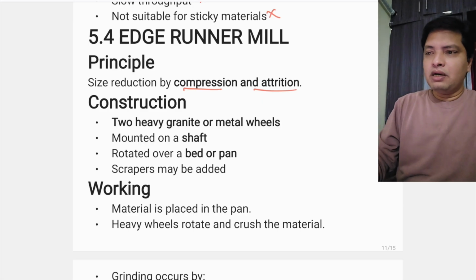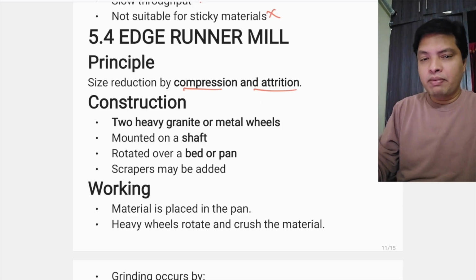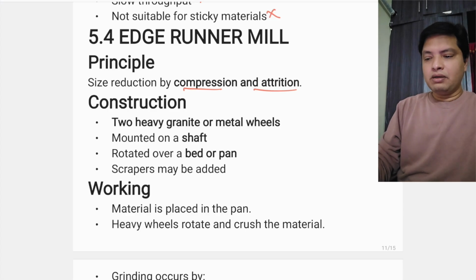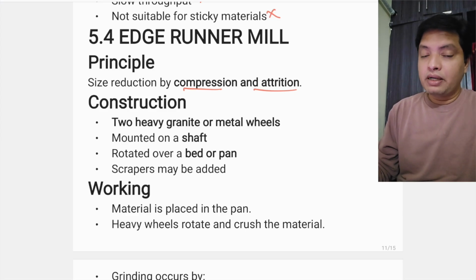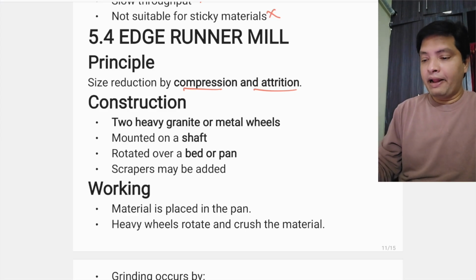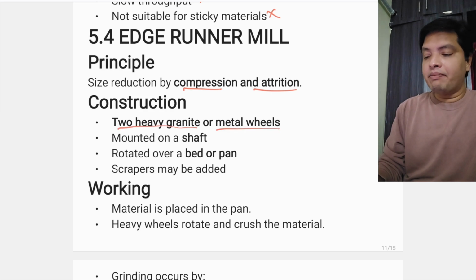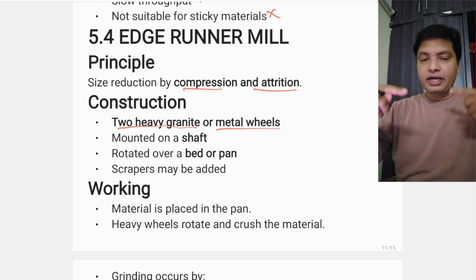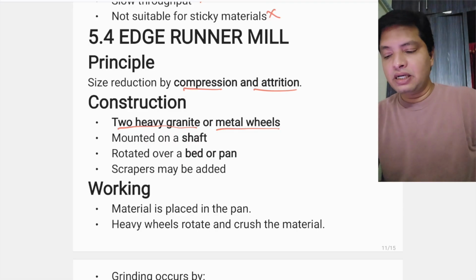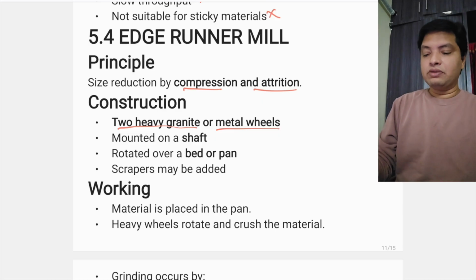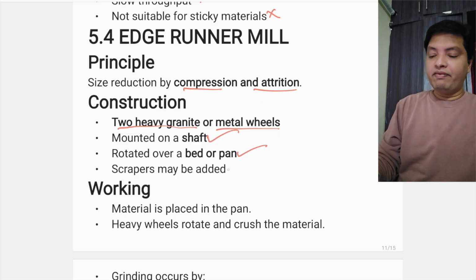Best thing is our idli batter or dosa batter is produced by edge runner. Two heavy granite or metal wheels will be there. These wheels will be rotating. Under this the particle will compress and also undergo attrition to get the particle size reduced. So a shaft will be there, and a bed or pan will be there.